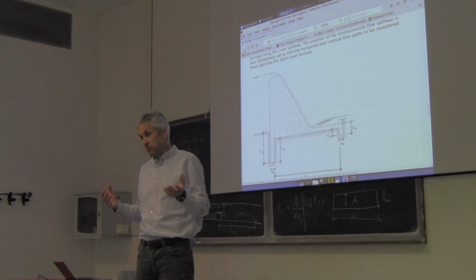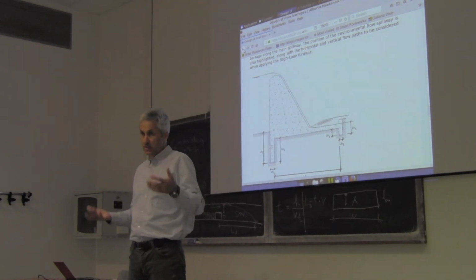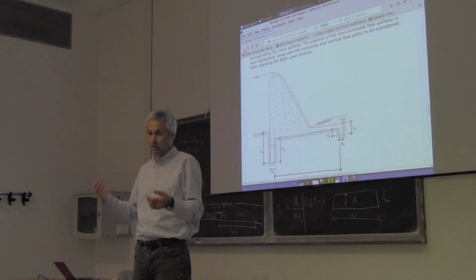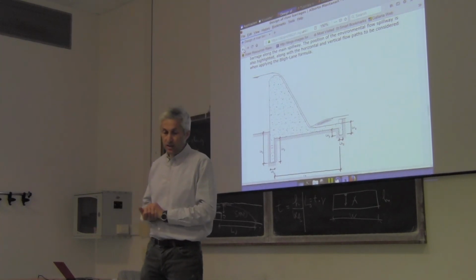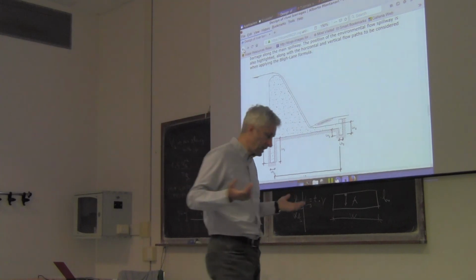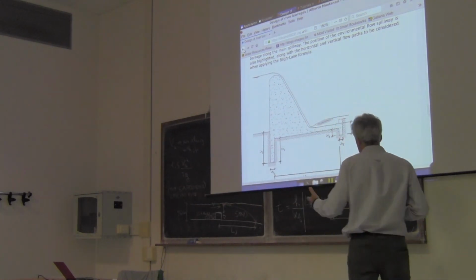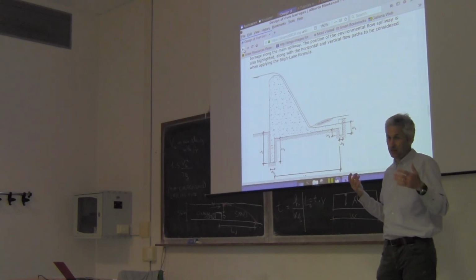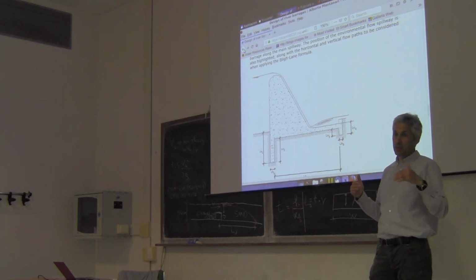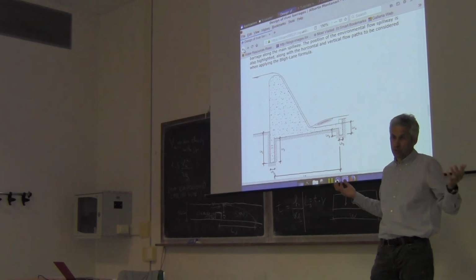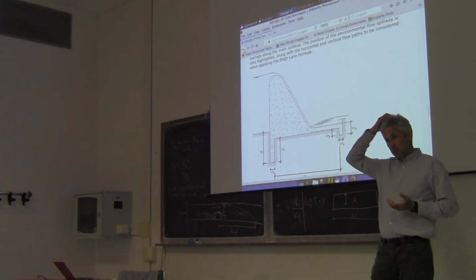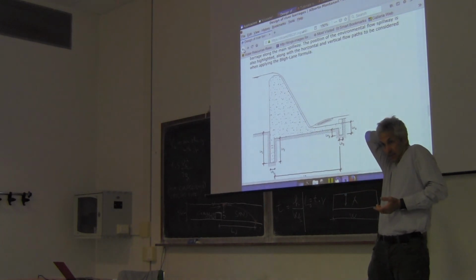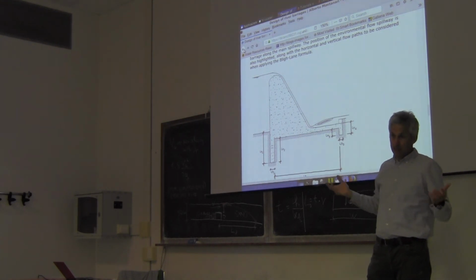This is typical of torrents, where there is a big difference, several orders of magnitude, between mean flow and max flow. Therefore, it's an attractive solution, but the problem is that sometimes we are not very sure that it can resist. Keep in mind that if downstream protection is removed, it means that probably the infrastructure is also removed, because once the river starts excavating downstream, the stability is rapidly undermined.